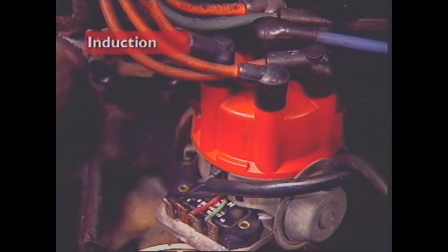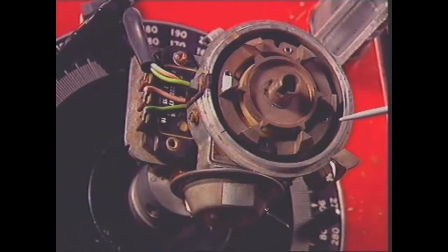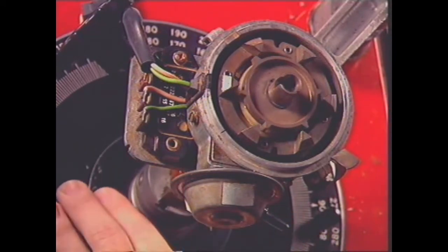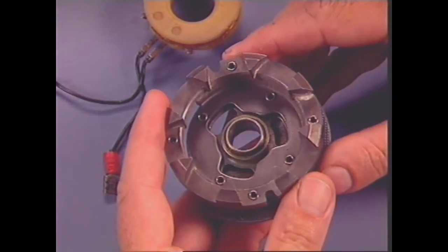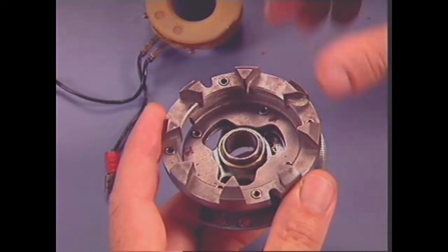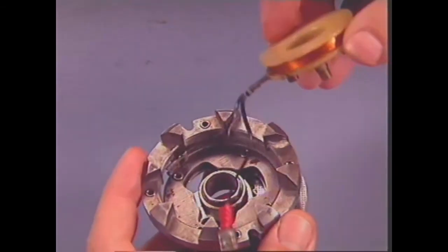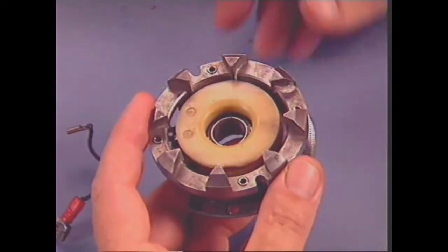In electronic ignition systems, the contact breaker is eliminated and the switching or triggering of the primary circuit is carried out electronically. In induction-type systems, a pulse generator has a stator mounted on the distributor body and a rotor unit called a reluctor attached to the distributor shaft. The stator has a circular permanent magnet with a number of projections or teeth corresponding to the number of engine cylinders, and a stationary coil of fine enameled copper wire wound on a plastic reel and positioned inside the magnet.